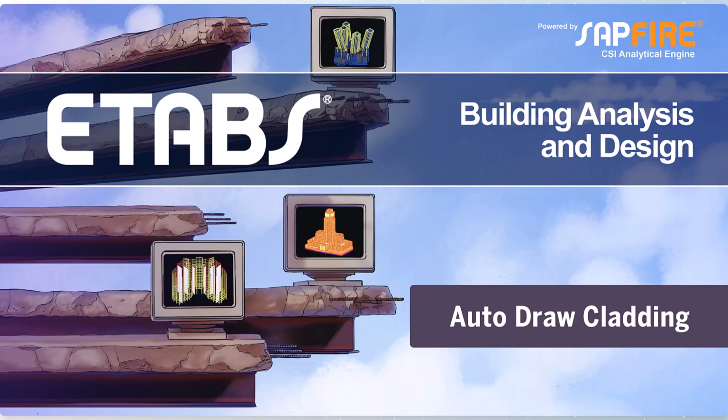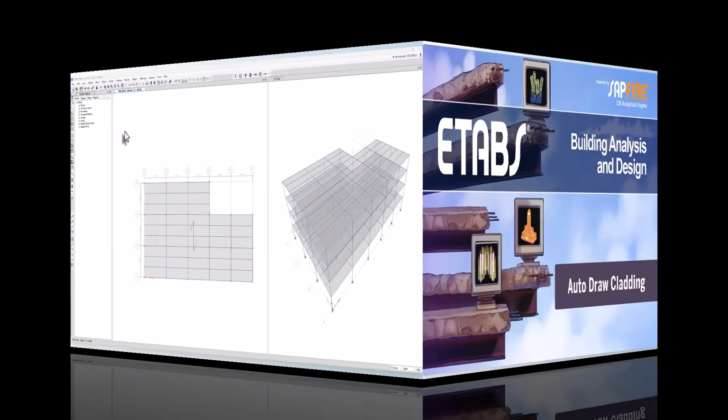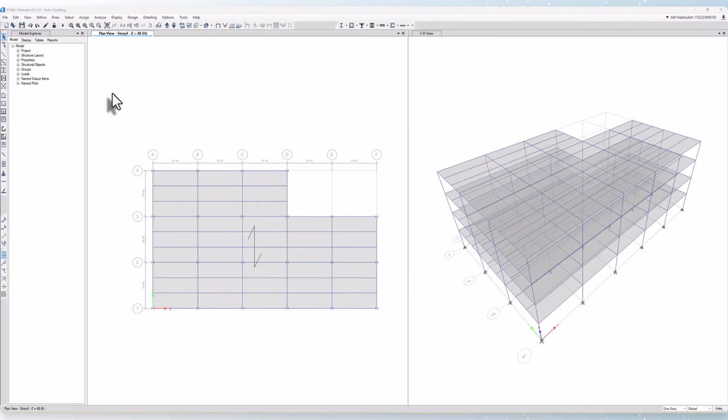In this video, we will discuss the capabilities of the Auto Draw Cladding option in ETABS. Let's get started. The intent of model cladding is to facilitate application of auto wind loads based on exposure of shell objects. The cladding consists of shell objects with the none section property that are added around the outermost perimeter of the structure. The cladding objects have no self-weight or structural properties.